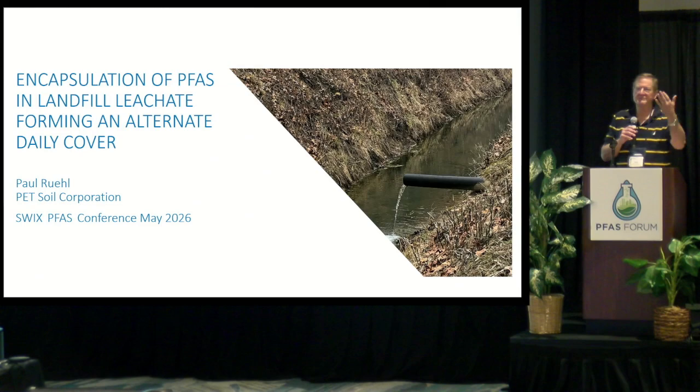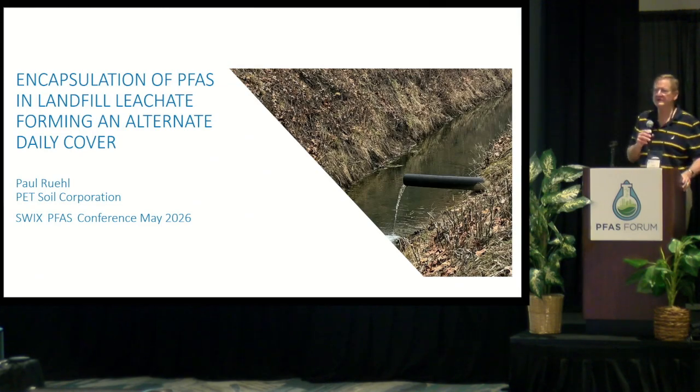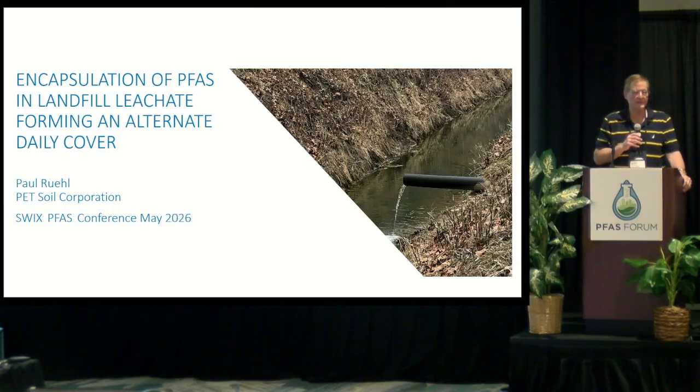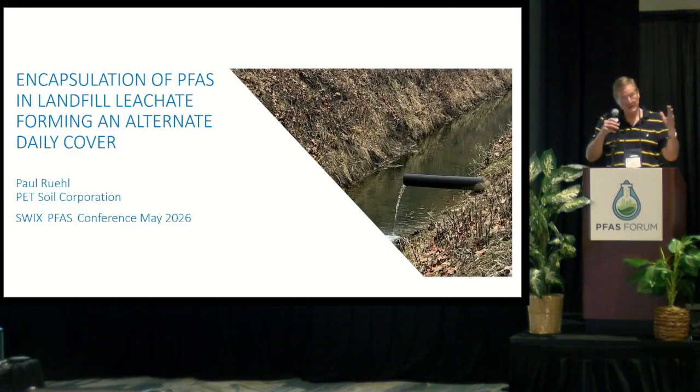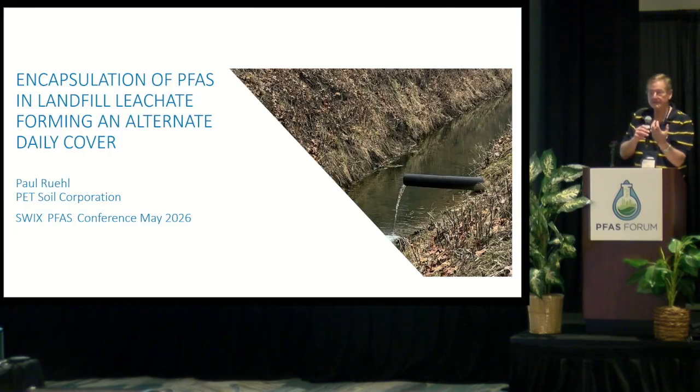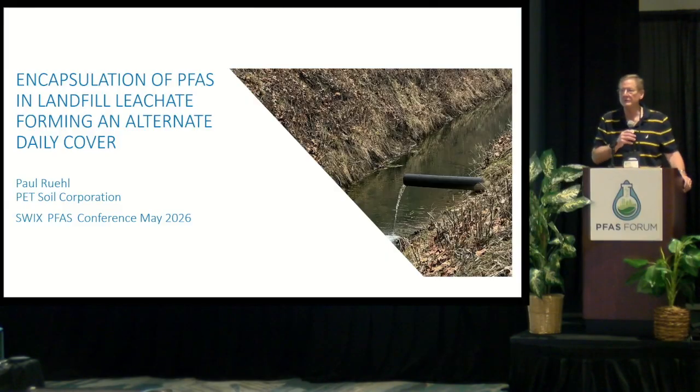And this was their output, 100,000 gallons a day of raw leachate, every day. They were running it through an RO system, which reduced the volume of contaminated water, and it concentrated everything, not just the PFAS. All the ugly nasties that were in the raw leachate got concentrated into 10,000 gallons. And the 90,000 gallons was discharged with an NPDES permit into a local river.